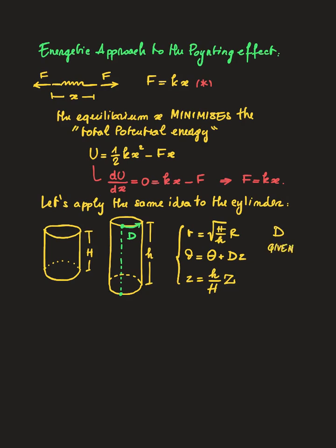So, I want you to do a very little application of the things that we did in the solution of the previous problem. Compute F, and after you compute the gradient of deformation, compute C, the tensor F transpose F. And when you compute these, compute the first invariant.